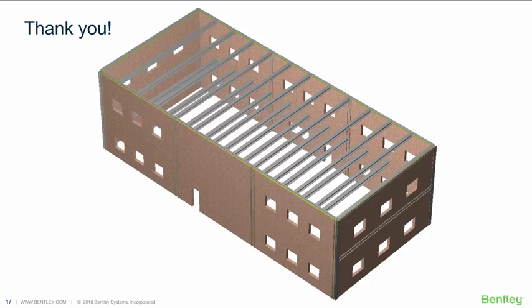I've dealt with a lot of concrete structures over the years, with shell elements in both the walls and slabs, multi-story, and I've found that starting with about a 4-foot maximum node spacing size works pretty well. I don't necessarily have a quantitative basis for that, but I find it's a good mix between precision and speed. So I'll usually set the mesh size to 4.